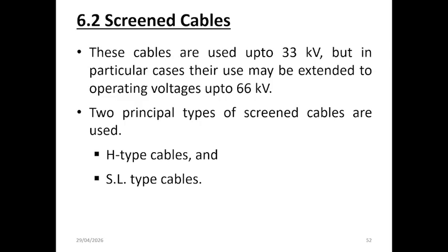Screen cables are designed to control electric field distribution more effectively than belted cables. The two main types of screen cables are H-type cables and SL type cables, each having a different construction method for managing electrical stress and improving insulation performance.